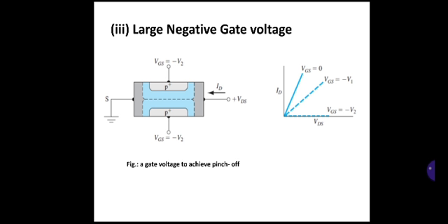For example, we assume that the potential at the drain end of the channel is the same as the potential at the electrode D. This is a good approximation if the source and the drain regions are relatively large, so that there is little resistance between the end of the channel and the electrode.